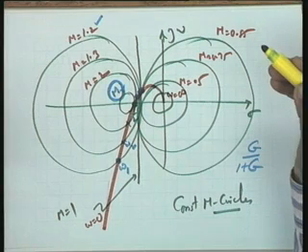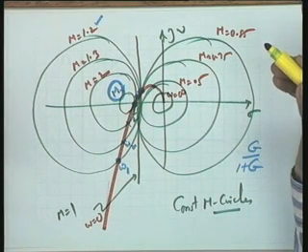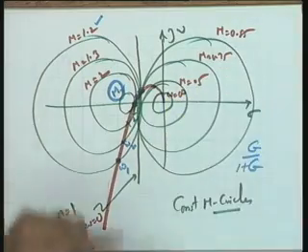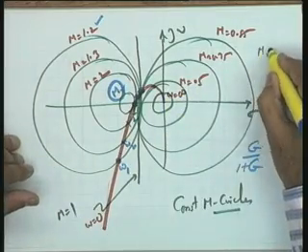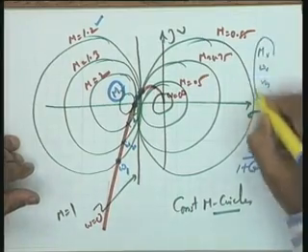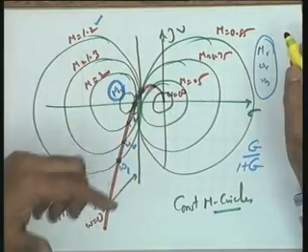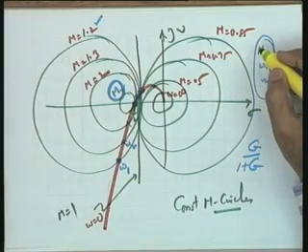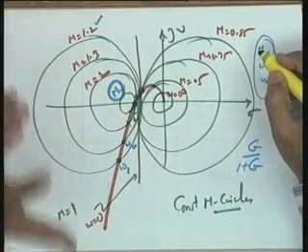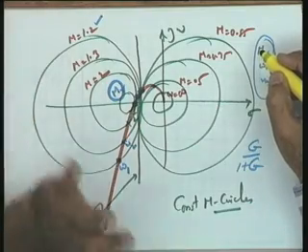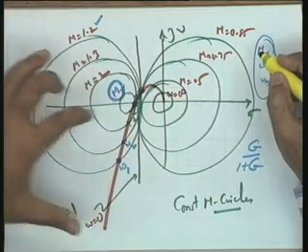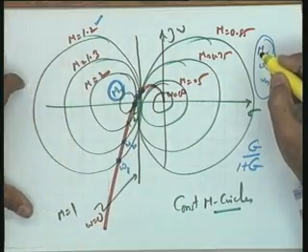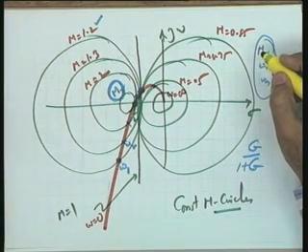Yes, please. So that means you are plotting an exact Nyquist plot over here. Yes. Usually we've been plotting very approximate plots. You see that in that particular case, I would like to say that if you are interested in the indices Mr, omega r, omega b, then as with the earlier phase margin and gain margin indices we have got approximately, a little variation is tolerable, because after all it is pre-CAD software analysis. So, I definitely do not say that any of these methods will give you exact values, but normally if you know how to do this without computer, then the possibility of making errors when you use the CAD software will be minimized.